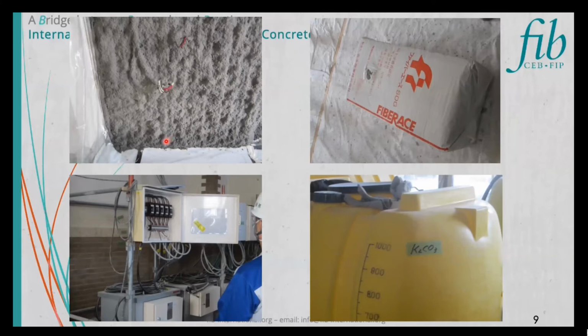This is a close-up of the electrolyte retainer. I cannot say whether this wire is connected to the reinforcing bar or the mesh anode. However, usually it can be distinguished by the color. In this repair, as an electrolyte retainer, cellulose fiber was employed. It was sprayed on the surface of the concrete and mesh anode.